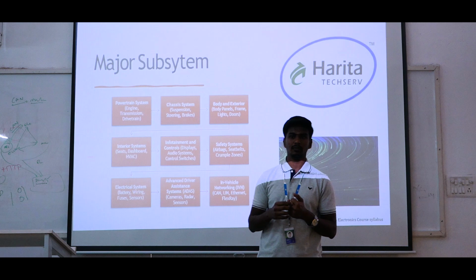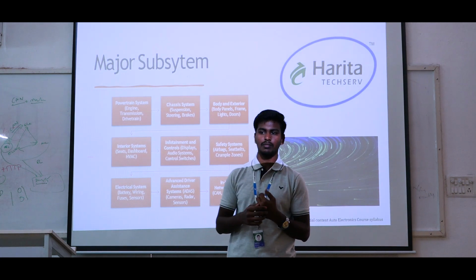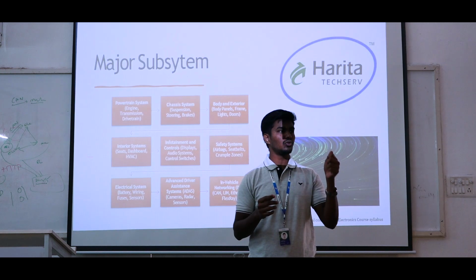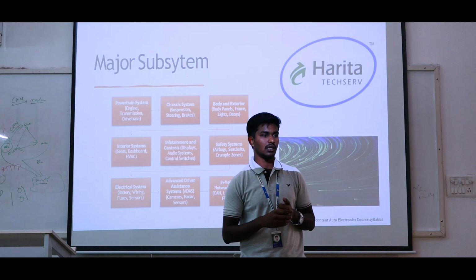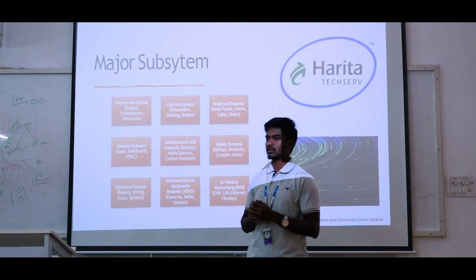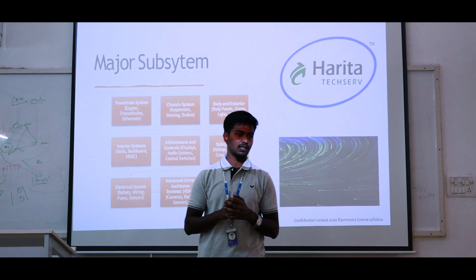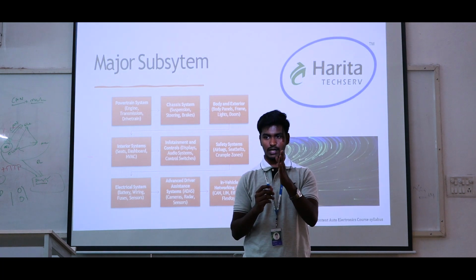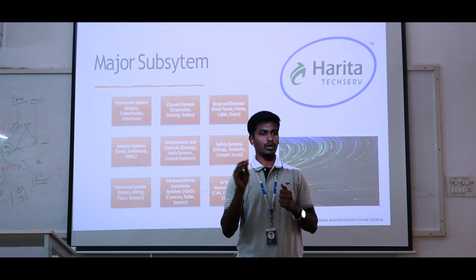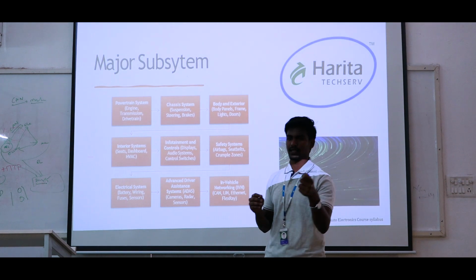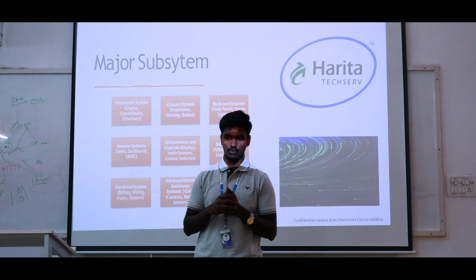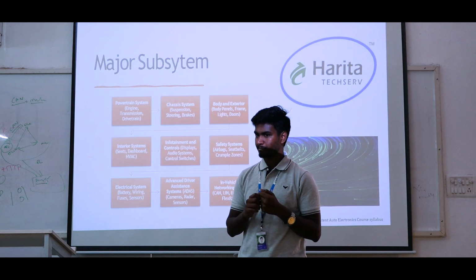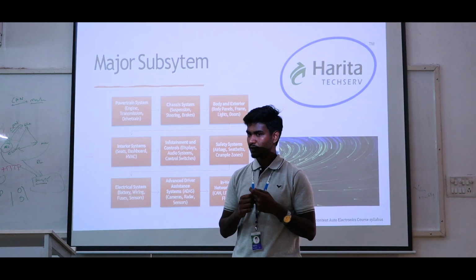For example, Mahindra recently launched electric vehicles, the BE 6 and XEV 9e. These vehicles have nearly 2.5 kilometers of wiring across the entire car's body control modules. Of that 2.5 kilometers, about 2 kilometers of wiring uses the CAN protocol only. The remaining 0.5 kilometers uses Ethernet, LIN, FlexRay and other communication protocols. In the system, all these are wired connections, not wireless.